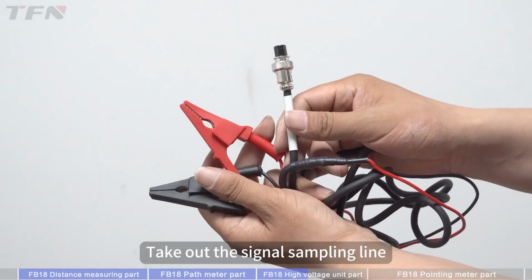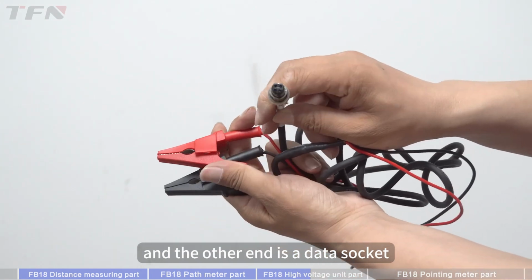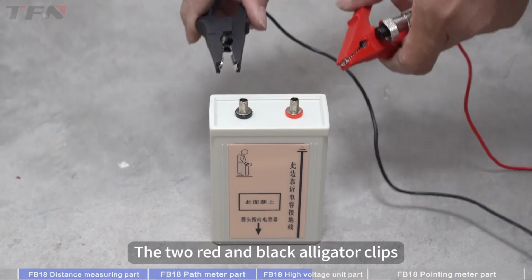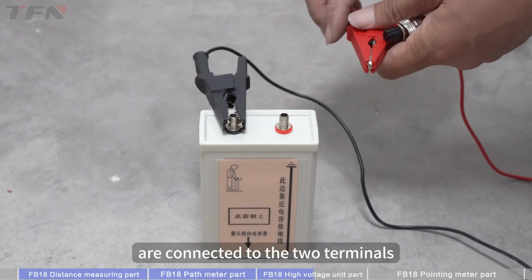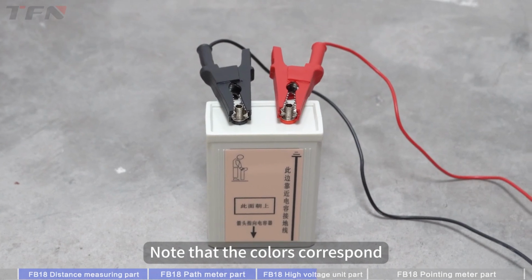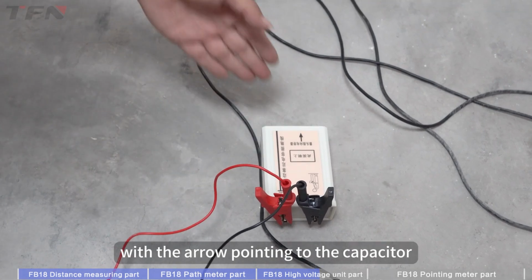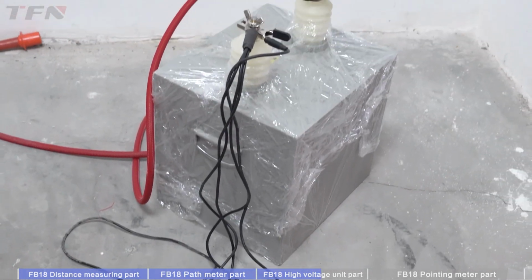Take out the signal sampling line. One end is 2 red and black alligator clips and the other end is a data socket. The 2 red and black alligator clips are connected to the 2 terminals of the current sampling box. Note that the colors correspond. Place the sampling box next to the capacitor ground wire, with the arrow pointing to the capacitor.